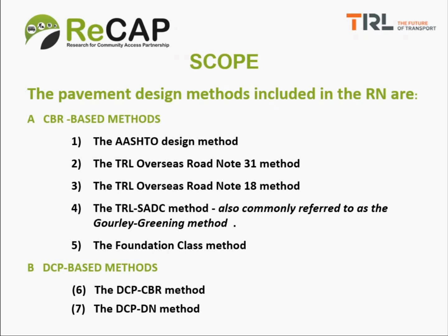But when we looked at existing roads that had performed well, certainly in 3 countries in Africa, we came to the conclusion that we could relax the specifications a bit. They didn't need to be quite so thick. They were working perfectly well. So in three countries, we did this study, and it came out with a revised design method. Again, quite similar to Road Note 31, but with slightly different outcomes.